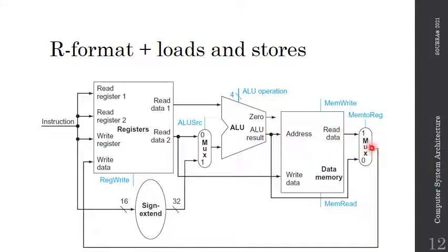Right? So here again, I'm using a mux to choose whether it's the direct result of the ALU in case of an R format, or whatever I'm loading from the memory to put back in the destination register. Right? Here you can notice something in blue, and we're going to talk about those later.